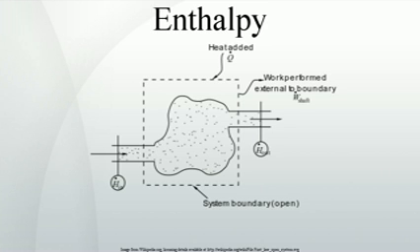Point C in Fig 2 is at 200 bar and room temperature, 300 kelvins. A Joule-Thomson expansion from 200 bar to 1 bar follows a curve of constant enthalpy of roughly 425 kilojoules per kilogram, not shown in Fig 2, lying between the 400 and 450 kilojoules per kilogram isenthalps and ends in point D, which is at a temperature of about 270 kelvins. Hence the expansion from 200 bar to 1 bar cools nitrogen from 300 K to 270 K. In the valve there is a lot of friction and a lot of entropy is produced, but still the final temperature is below the starting value.